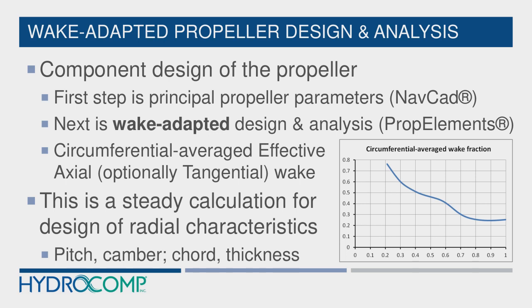Now, as mentioned, this is a steady calculation, but its objective is the design of radially varying characteristics: pitch and camber, principally for thrust and power loading, efficiency, and what's called shockless entry, the shape of the camber to minimize pressure peaks at the nose for cavitation assessment.